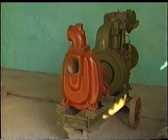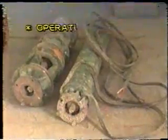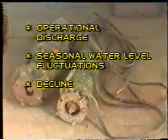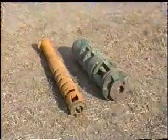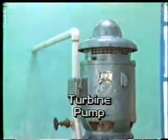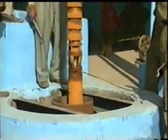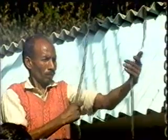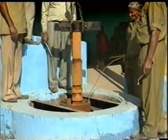Selection of pump is important for efficient operation of tube well. It is based upon operational discharge, seasonal water level fluctuations, long-term decline of static water level, pumping water level, etc. Submersible pumps and turbine pumps are most commonly used. Selected pump set is installed in the well. The installation of a pump is a very important step, leading to efficient operation and maintenance of tube wells.